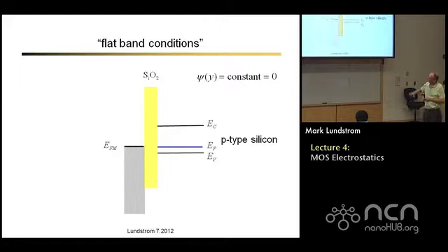Okay, so in the normal direction, we have this gate, and it has some Fermi level, so I'll call that EFM, the Fermi level in the metal. And all the states below the Fermi level are filled in the metal. Then we have this thin insulating layer. And then we have a p-type semiconductor in the channel underneath. And if I had just the right metal and just the right doping in the silicon, all the Fermi levels would line up when I apply 0 voltage.